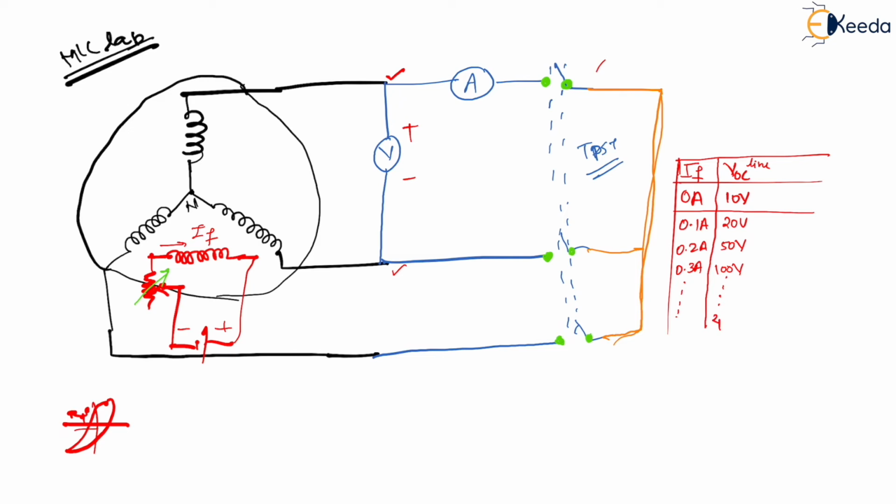And then at the end what we can have is, let us say, 450 volts. Let us consider that this is the rated voltage. Because if you don't keep to the rated voltage, if you increase the field current even more than your rated voltage, what will happen? Insulation problems and all may occur. Anyway, don't think about them, it's okay.